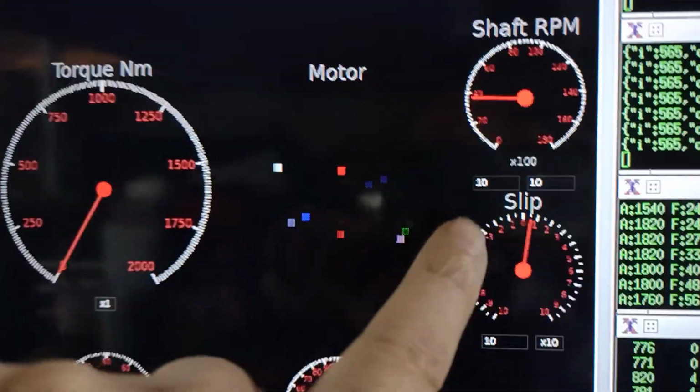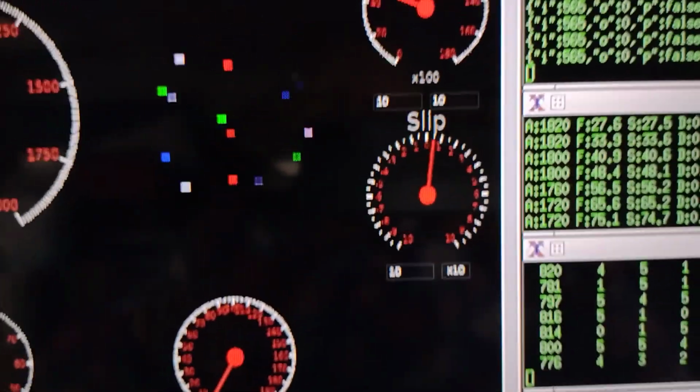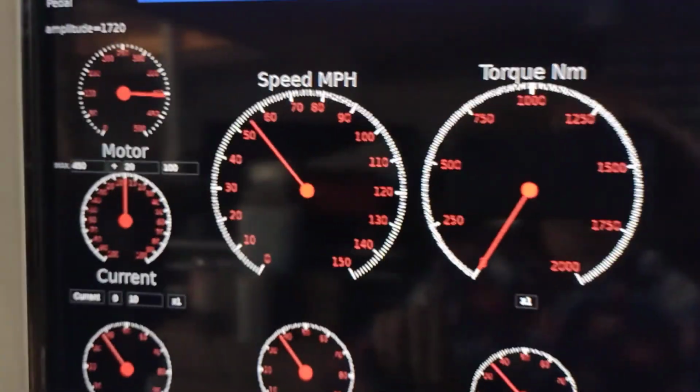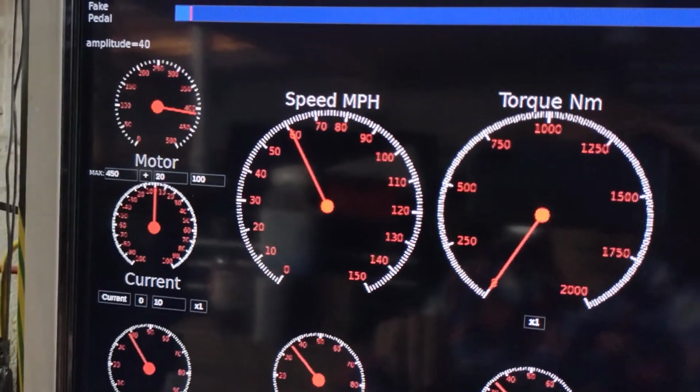Now then, I'm thinking this is on, so I'm going to just press it down and bring the motor on. The motor's down there, you can't see it, but you'll hear it. So as I press it down, there you go, and now you can hear it going up, and see how the frequency is increasing and the slip is kept within certain bounds. Right, that's the equivalent of 60, so I'm going to back off the amplitude.